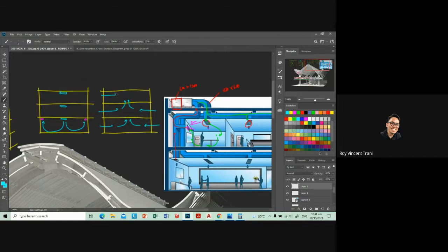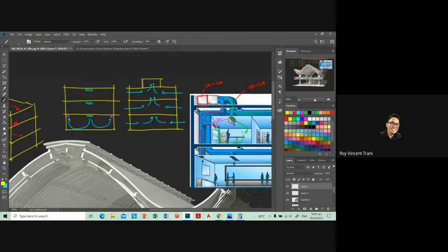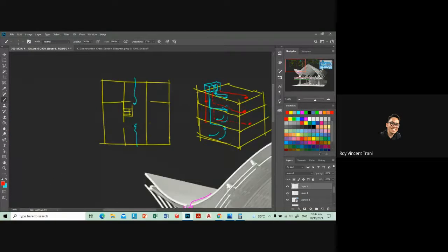I've seen a work where they put a vent stack in, and then there are no windows around the floor plan, so the vent stack won't work. They're just putting in a useless atrium. As it goes higher, the air becomes hotter. So usually you would need to have vent stacks in an open hallway, not in the middle of a hallway that's enclosed on four sides by rooms.